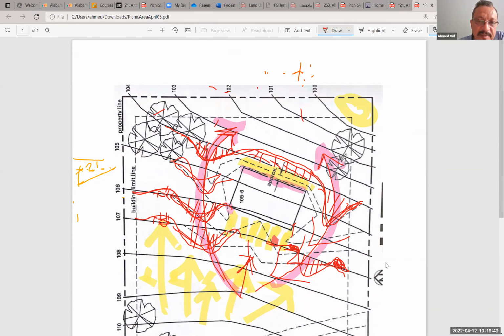When I'm filling in the back of the building, I'm extending the slope. So instead of being like 40% or 30% or something, it becomes like 1 to 20, or 20% or 18% or maybe 8% or 10%. But this might need to move earth further.